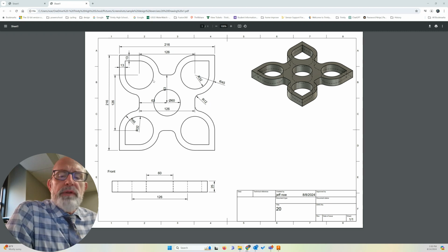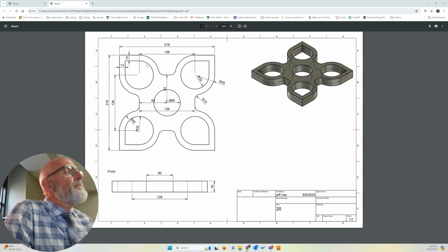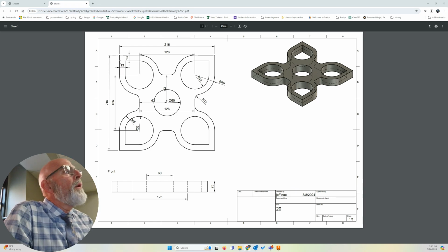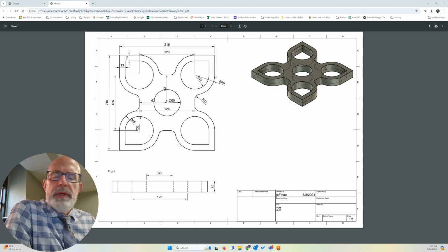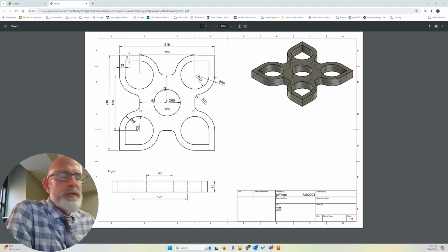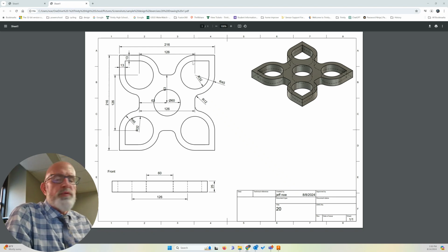But if I look at it closely enough, it looks like we have a circle, okay, or an arc, but we'll use the circle tool in this particular case, with one end that comes off as a square. So here's the center of the circle. We know that the radius is 45 millimeters where that circle ends and the straight part starts. We know it's 45 going this direction too.